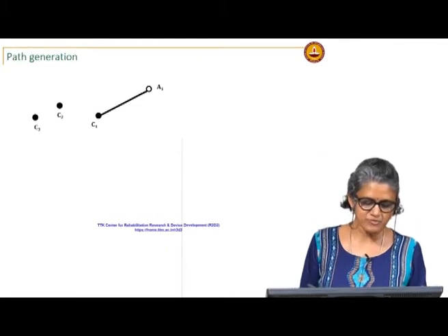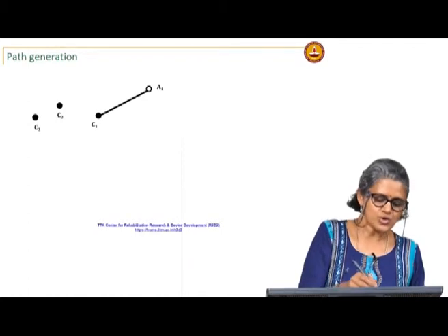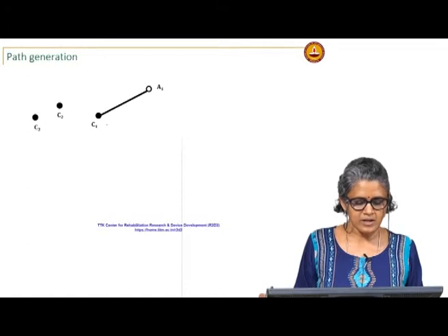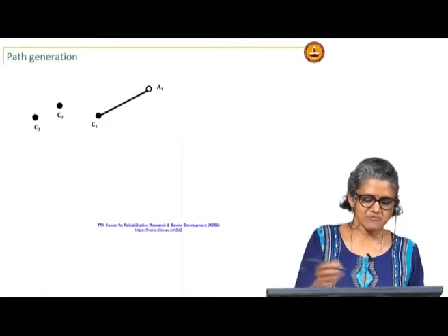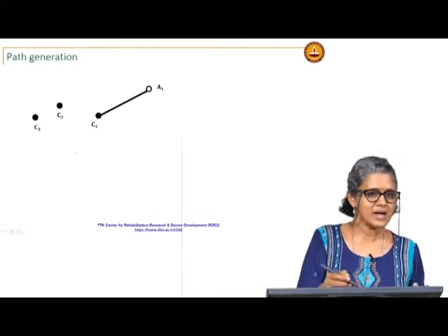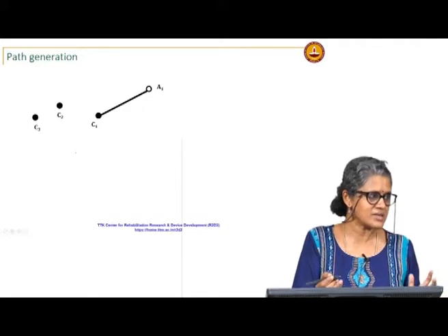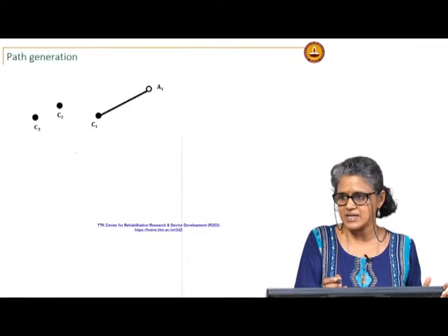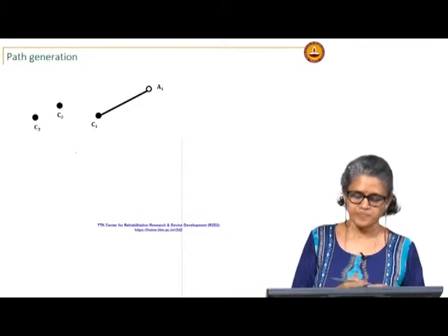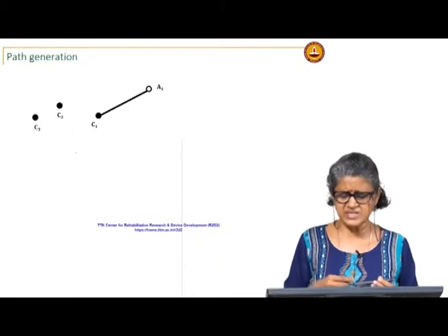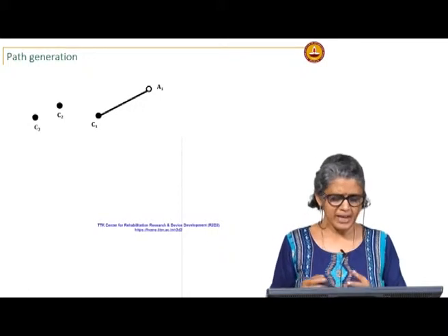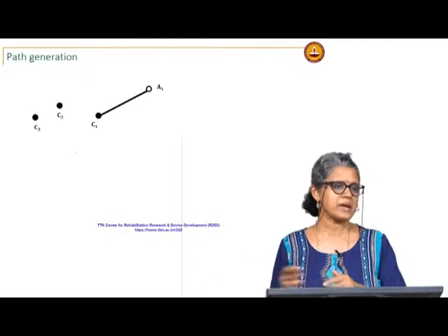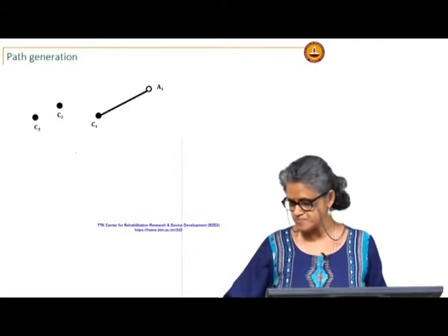So, you could have C as one of the moving pivots, in which case you would do your typical procedure, and then you choose A as another moving pivot and you can synthesize the linkage. So, path generation is fairly simple, and again limiting positions, driver dyad, the same things apply to all of these.